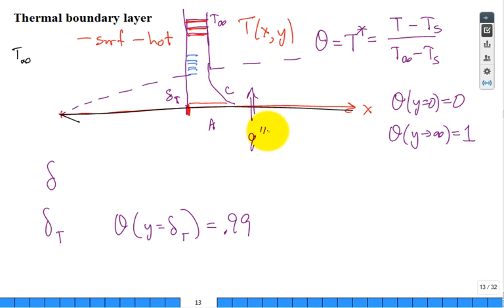Okay. How am I going to calculate Q double prime? Well, at the fluid, isn't there still no slip? If there's no slip at the surface, at that millimeter, micron, whatever layer, very thin layer of fluid is stagnant right there, you have to have conduction pushed into the fluid. So they'll say at the surface, it's Fourier's law. They'll have minus K of the fluid, not K of the solid.